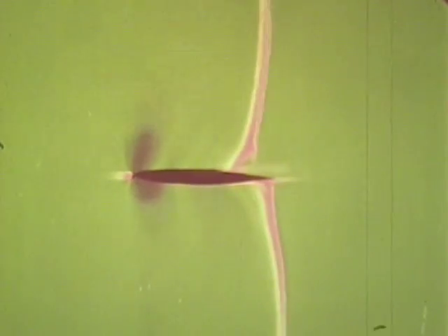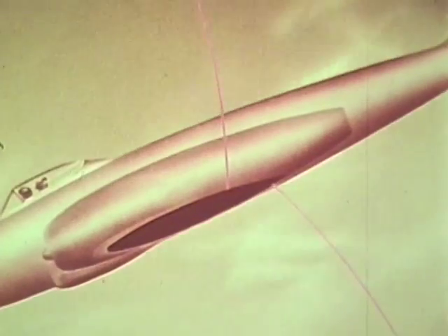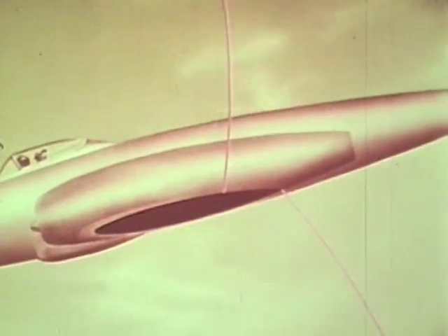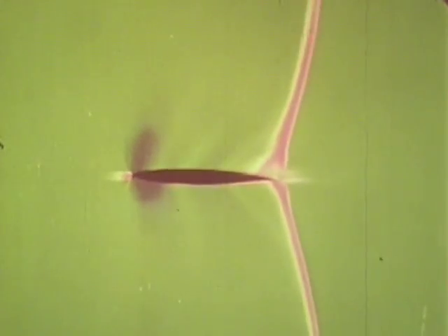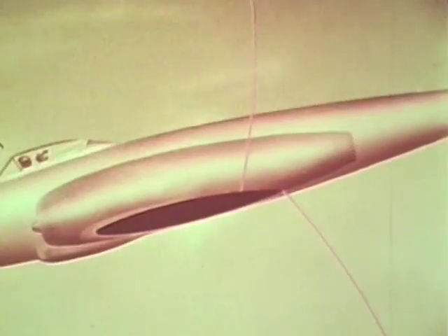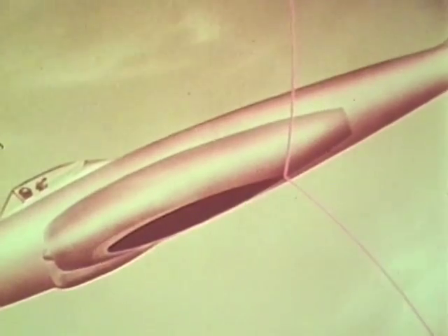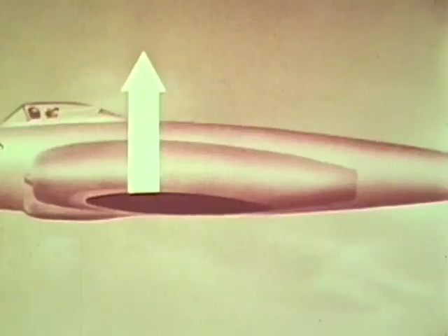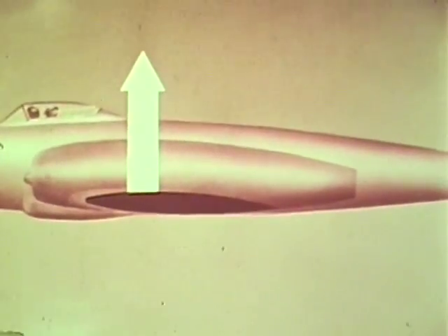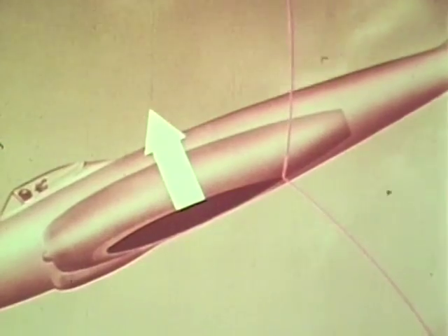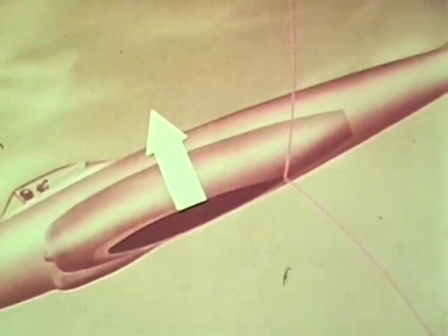As the Mach number increases, the bottom shock appears and reaches the trailing edge before the top one. This forces the nose up a little. Finally, the top shock also moves to the trailing edge, making the aircraft go more nose down again. Most aircraft don't do all of these things, but the center of lift always shifts toward the rear when passing through the transonic range. So all aircraft suffer a final nose-down trim change.